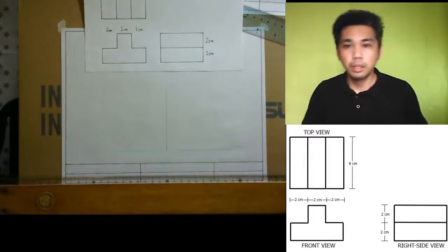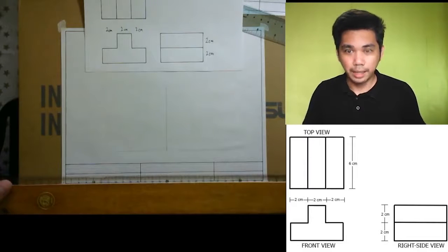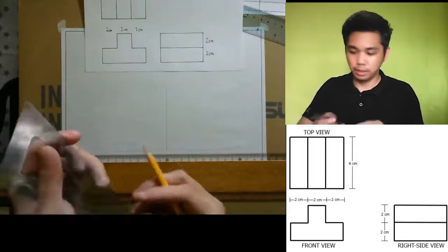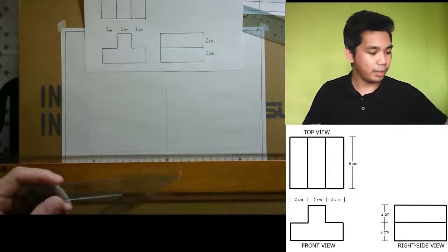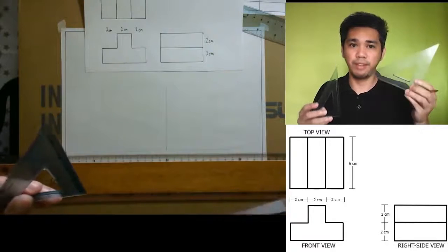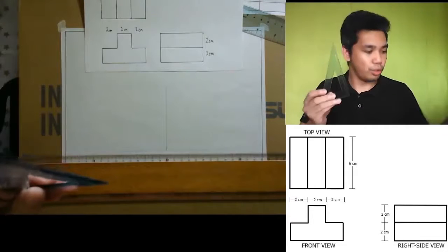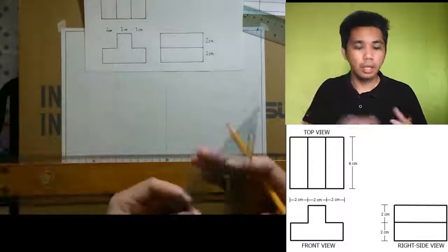Now, since we already know the topmost line, we will create our slanting lines, the projected 30-degree angle. Again, which of the two should we use? A 45 by 45 or a 30 by 60? I'm guessing you got the answer correct. We need a 30 by 60 triangle.